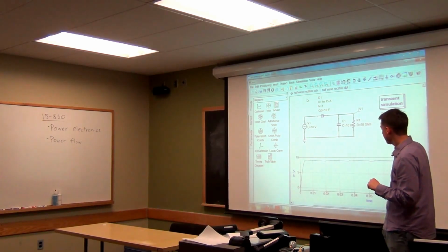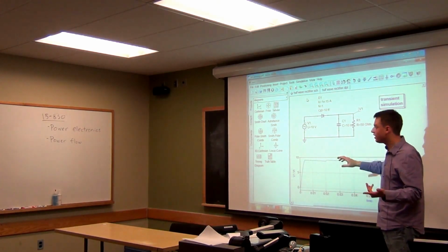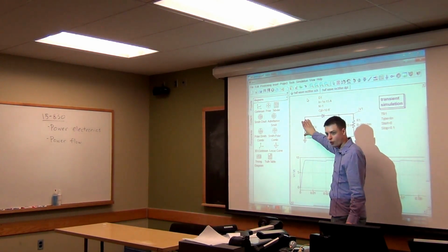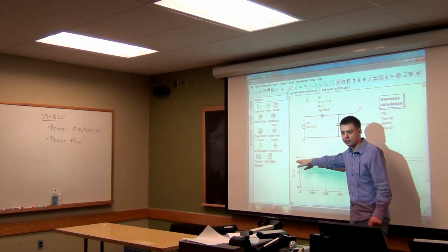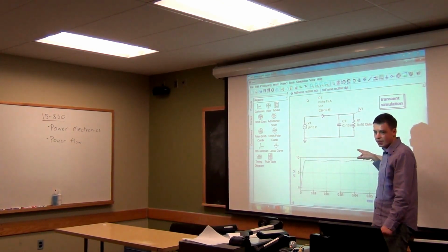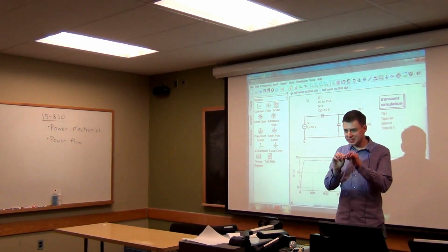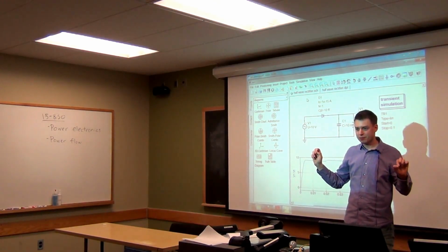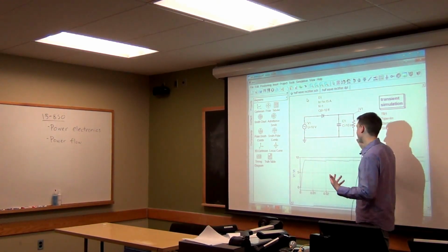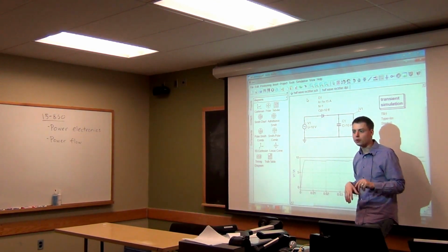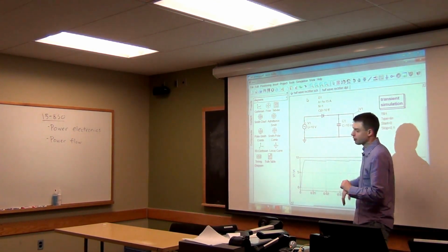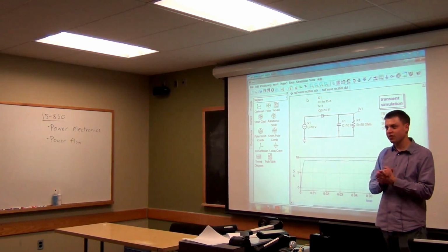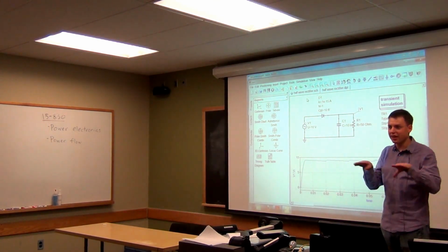Right? So look what we've done. We've taken an AC source, and what we get out on the end is a DC voltage. Again, it's not quite perfect DC. It isn't exactly flat, but it's good enough. And by adding other elements here, like we can add an inductor too, which can smooth it in a slightly different sense. And then we can also increase the capacitance of this. We can get something that's arbitrarily close to a flat line there.